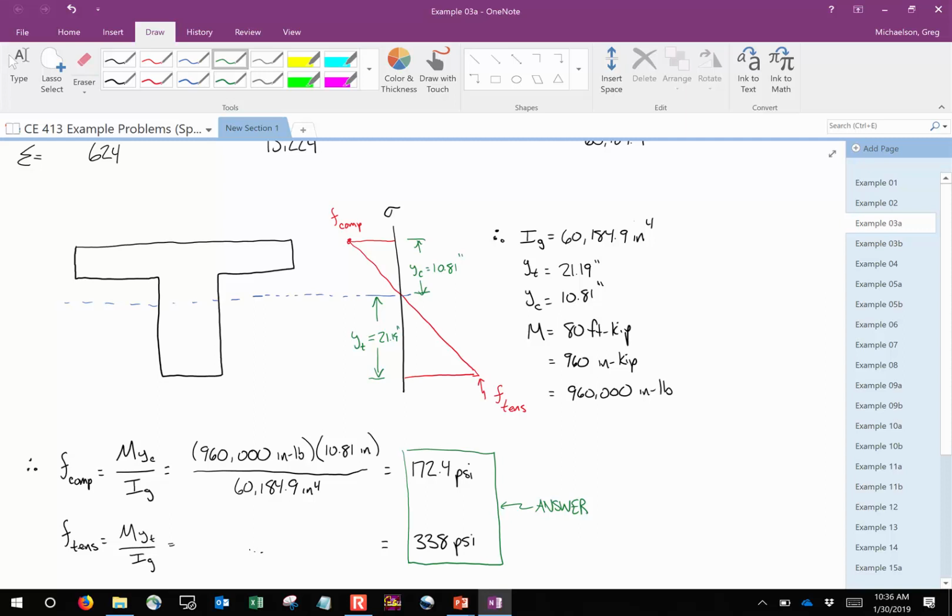Yes? Is there any factor you would use the compressive stress as a baseline for, like how we use the tensile limit right there to tell whether it's going to crack or not? Can we use the compressive stress to tell if it's going to act a certain way or not? No, but we've got a lot farther to get in terms of what happens after it cracks. Just because the tensile region cracks does not mean that the beam is done by any stretch of the imagination. In fact, if you look at the cracking moment of a beam versus its actual nominal flexural capacity, they're nowhere near the same. So beams can handle a whole lot more beyond cracking moment. So we're just getting to, like, stage 1. The way that we handle that is different, and I don't want to confuse you, but we're going to get there, because there's a stress block approach and all that.